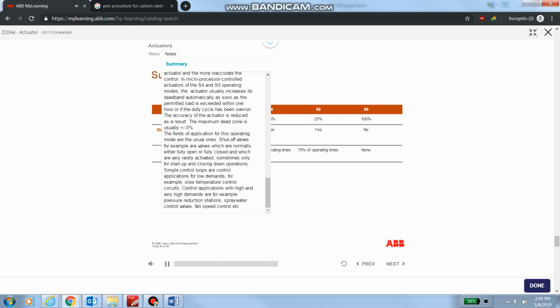The efficiency is affected to a great extent by the friction inside the gearing and the mounting. For example, with a total efficiency of 16%, 84% of the introduced power in the gear unit is lost through friction in the form of wear and tear and heat. It is immediately clear that such a gear unit construction is not suitable for continuous operation.